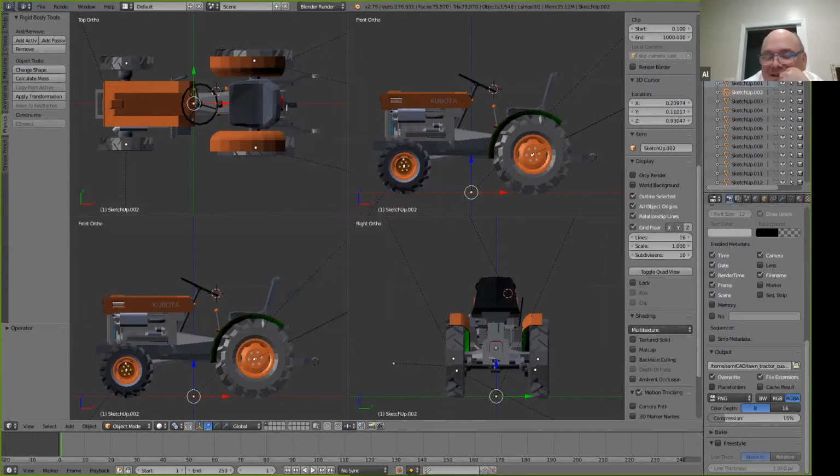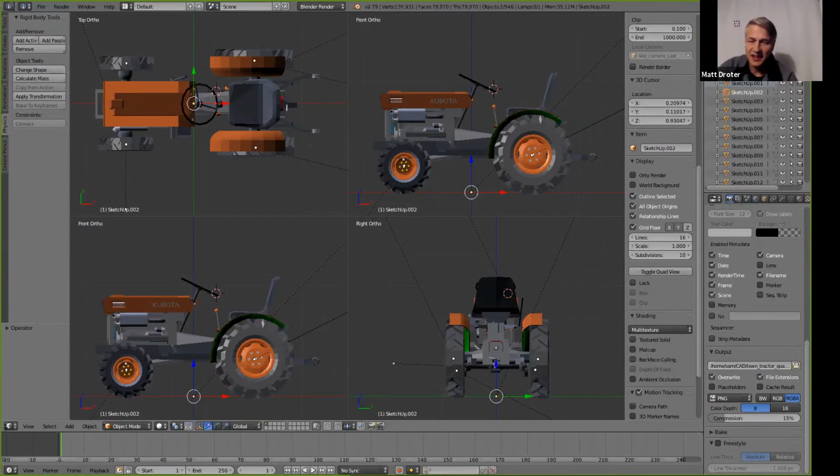Is this orientation, I mean, certainly Z up, I'm very familiar with Z being up and X and Y being left and right, as looking at, say, the front ortho, your top right. Right. Okay, so you're having to tell ROS that what I consider to be a normal orientation is 180 degrees off. You see that the red arrow is your X-axis, and that's pointing towards the rear of the tractor, instead of the front. Right. Exactly. So the orientation is incorrect.